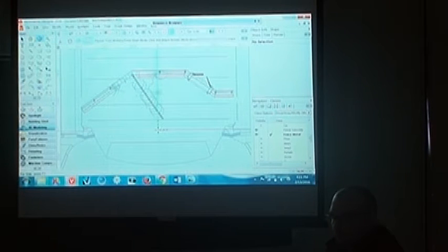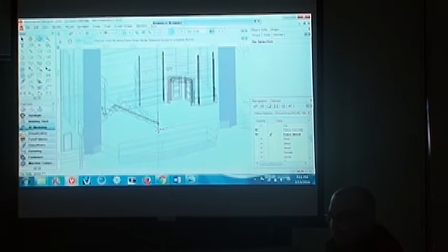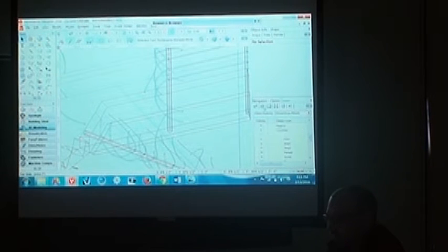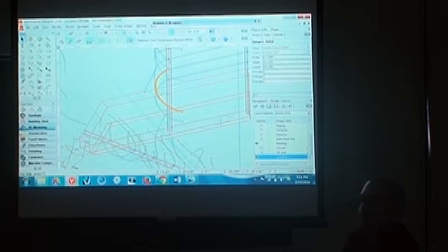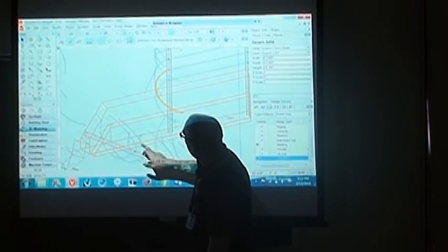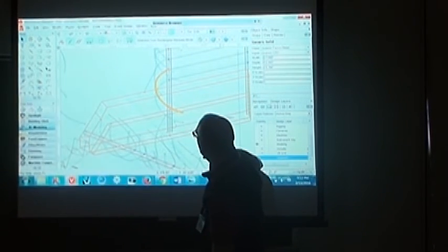So I'm just going to mention the other thing I used the custom working plane for. These crazy curved wires where it's supposed to look like the T-Rex broke through them. I took the 3-point working plane, the way of setting the working plane with three points, and I chose a point here, a point down at the ground, and a point over here.